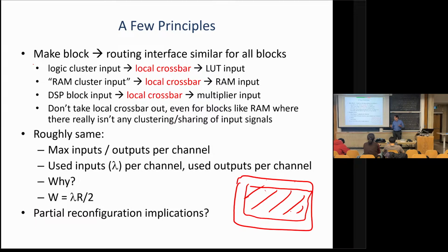Even if you take out the whole accelerator, it goes from compression to encryption, you didn't take down the server. But if you completely reset the FPGA and it's actually the path for the server to talk to the Ethernet, you probably took down the server. So that's another very disciplined use of partial reconfig.